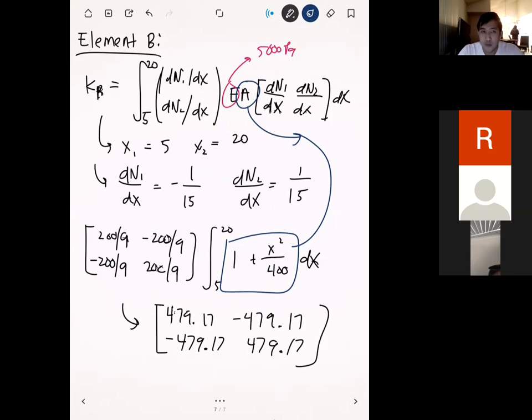For 1D problems, you don't see any anisotropy because we're just going in one direction. But once we get to 2D and 3D problems, that's when we can start to introduce that the Young's modulus is stronger going this way versus this way. And you can account for that in the formulation as well. So this way of doing finite elements off the boundary value problem is really versatile. You can basically solve anything with it. All right, any more questions on this?